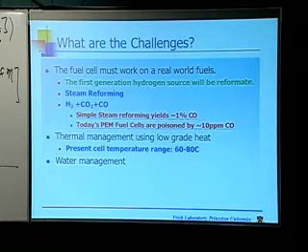So you do all those things, and then you polish off your final feed stream through a palladium, or I guess people like a palladium silver filter now. Palladium will let the hydrogen through, keeps all that CO and CO2 back where it belongs. And you get a tank of hydrogen like the tanks of hydrogen that we all use in our labs, and those have less than 10 parts per million of CO in them, you'll be happy to know, and your fuel cell will run fine.